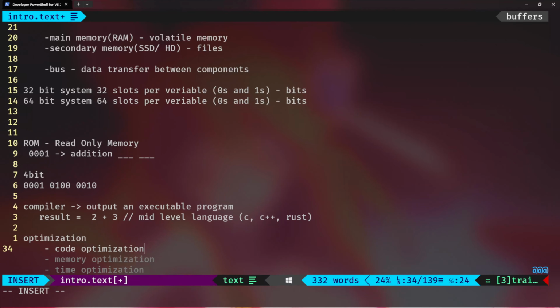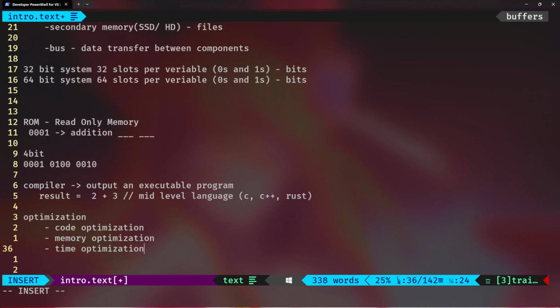Let's say I want to perform four additions, and my CPU already has four cores. Rather than taking one core and giving one variable at a time and doing one addition at a time, which will take four cycles, let's say I put four values inside the four cores, and then I ask them to simultaneously execute, and each core has its own ALU.